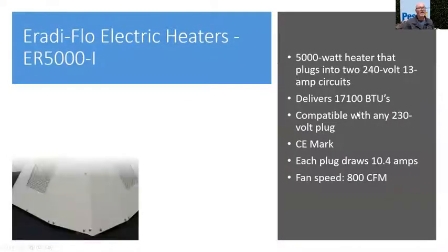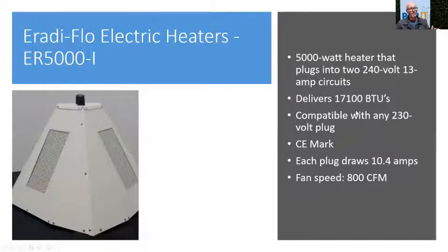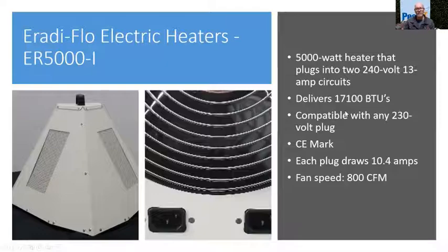Now, looking at the slightly larger brother of that, which would also be incorporated into the heat treatment kit that you would look at with a 240 volt option, you'd have 2 kettle ports, and you can just see there's the front of the unit and the rear of the unit. At the fan, you'll see two typical terminal ports or kettle ports, whatever you want to call them. Now, the idea of that is that both of those incorporate a 10.4 amp input and therefore has a 21 amp consumption.